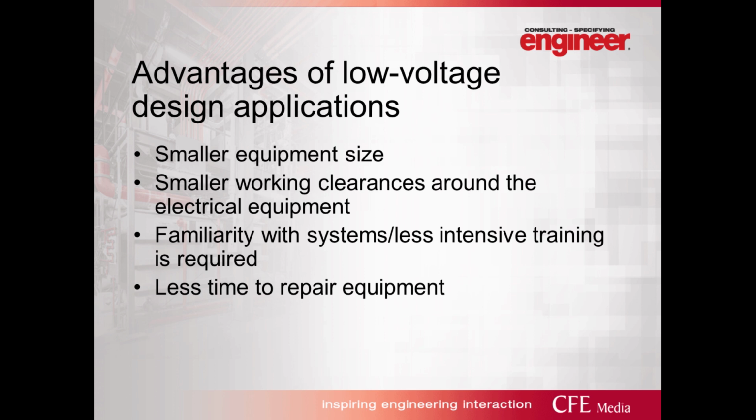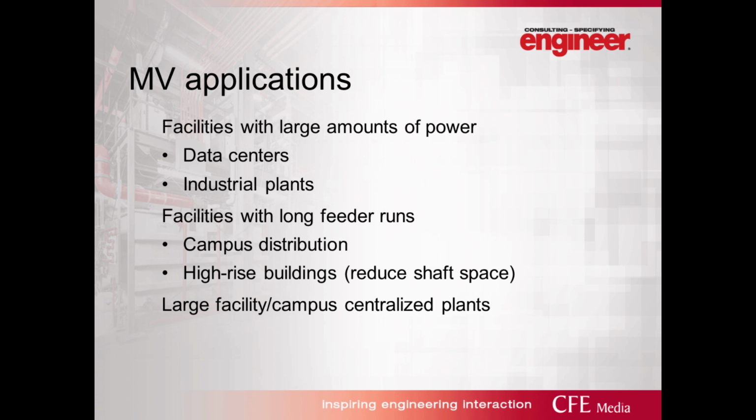In most of my projects, we are bringing a low voltage 480 volt system into the building and then letting the utility deal with the maintenance and installation of the medium voltage utility transformer. The utility also typically will terminate and maintain the primary medium voltage cables to the utility transformer. So this makes the maintenance and installation much easier for the customer. Back to you. Thanks, Jane.